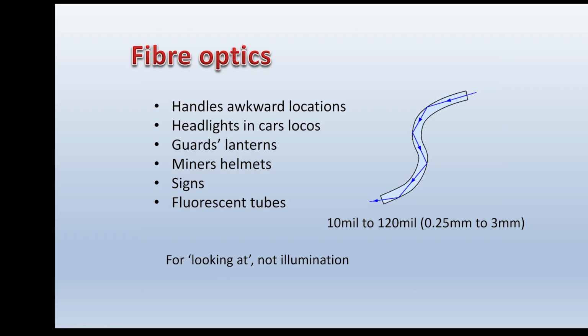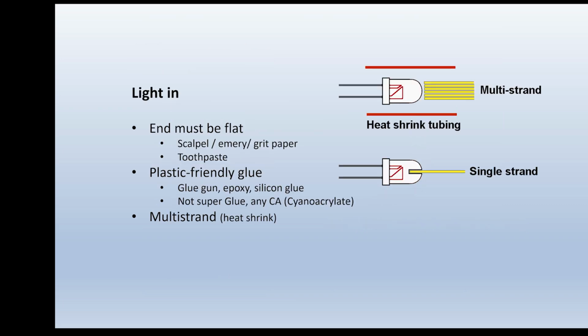Generally speaking, if you're using a single strand, you're not going to get much light, so it's not intended to illuminate things. It's to be looked at in awkward situations like the miners' helmets, guards' lanterns, and so on. The ends must be flat to get the maximum light transfer. If you're really keen, you can actually drill into the lead body if you're very careful and don't go too far, and get the maximum light transfer that way for a single strand. It takes a bit of preparation to get the best from it, but it's very useful.